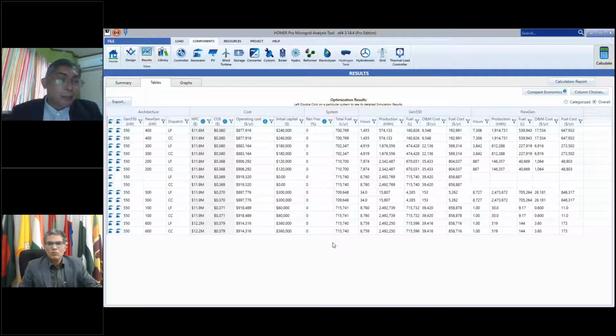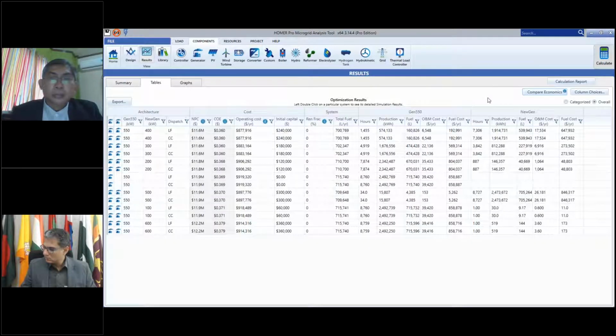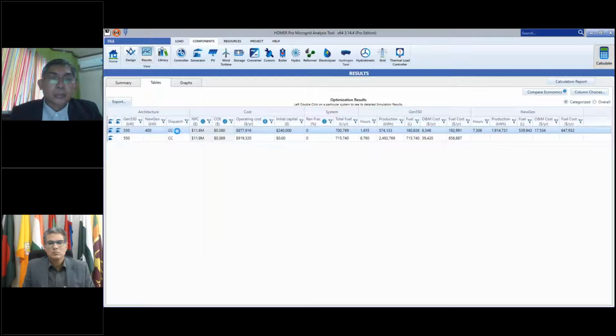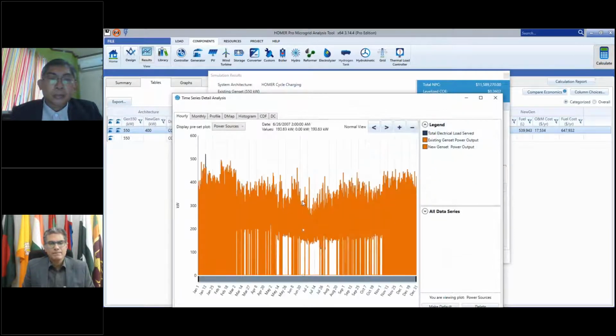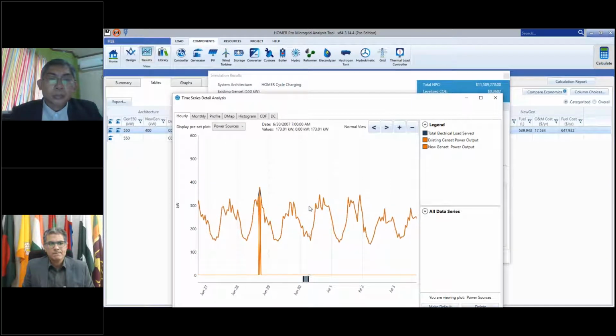Ramp rate? Sure, but it does it to the limit of the resolution of the analysis. So if you're typically doing hour-long time steps, you're not going to be able to model the ramp rates. And even at a 1 minute time step, it's true that the larger utility scale coal-fired plants ramp slower, in megawatts per minute, but your diesel generators don't. So, although you can model